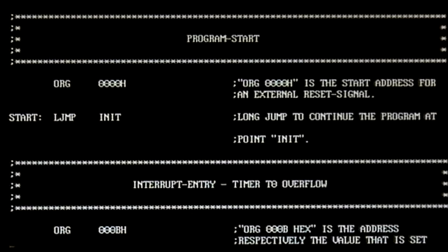If the microcontroller program starts after the system is switched on via the reset signal at program address 0, a jump command is sent to the program counter address 100 hexadecimal. I called this entry point init.